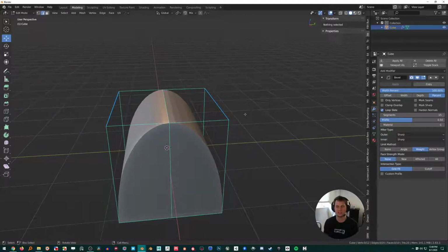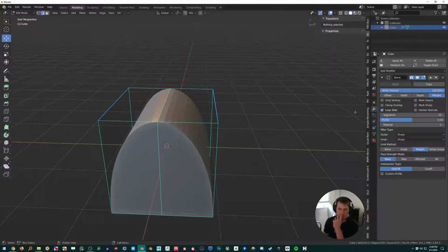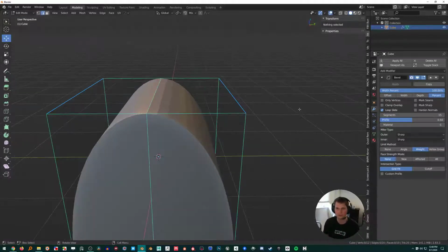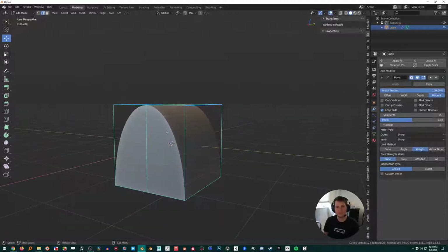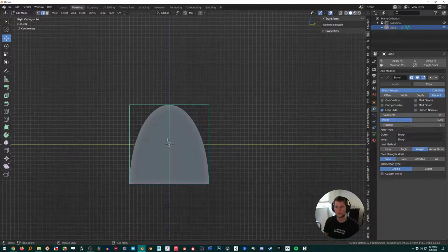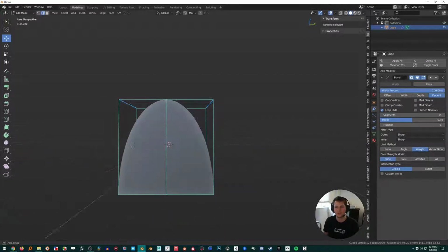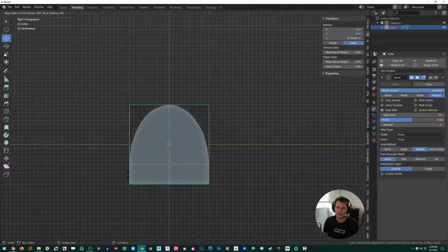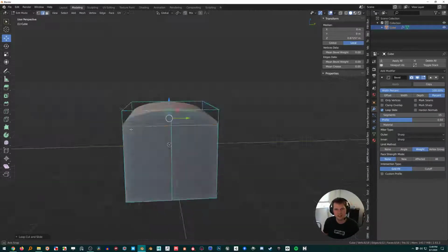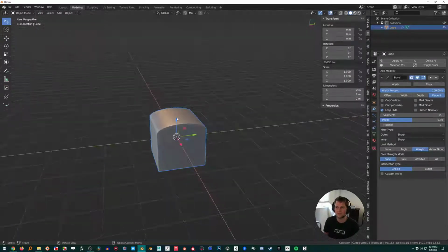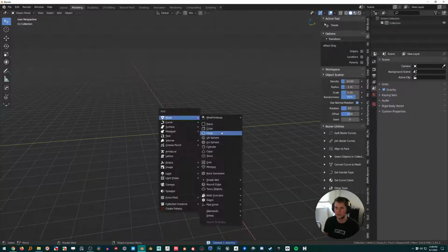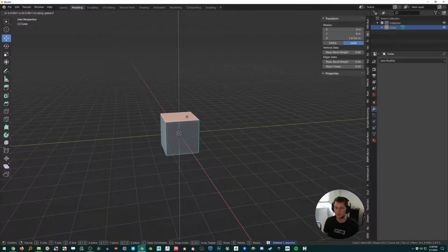You don't really need it for percent, because it's not going to give you the results you want. It's going to clamp the percent. The nice thing about using percent is you have full control over how oval or how round your bevels are. So in this case, I can just add another edge loop right here, and I can control exactly where I want this. I'll give you another organic case. So like using it right here.